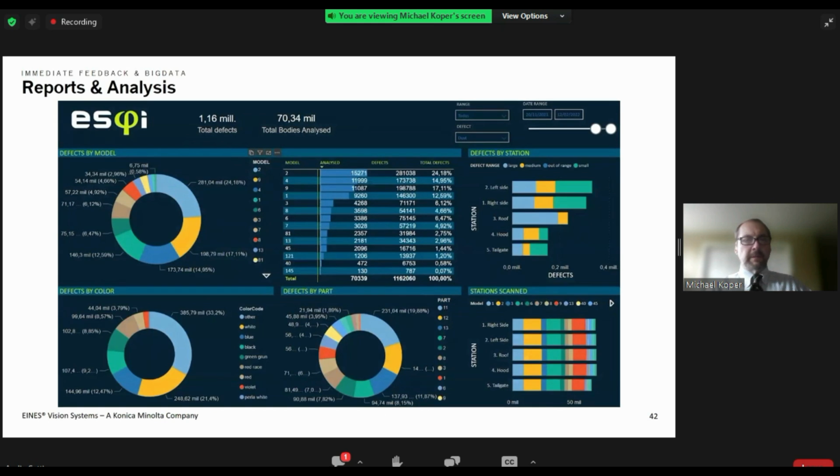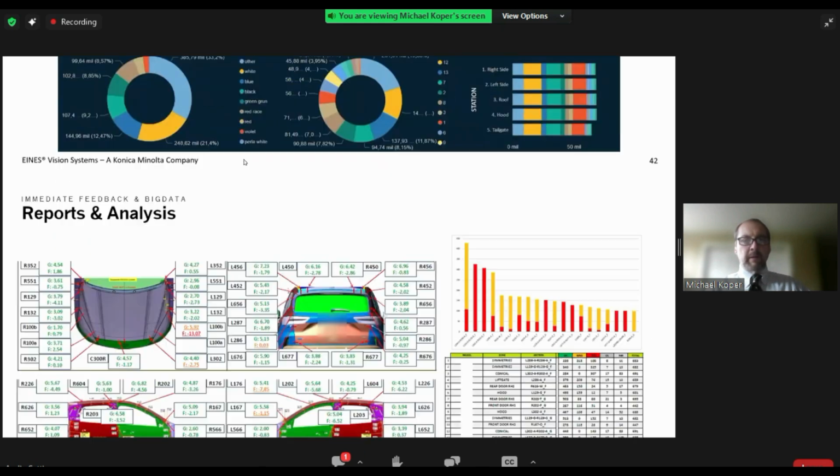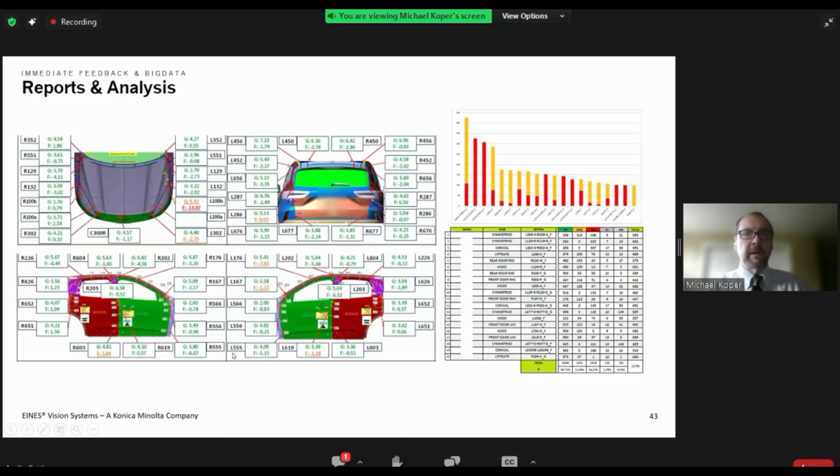And then here in our flush gap system, right, we're looking at not only the number of points. So we have several different systems that are in the working at different OEMs right now, where we're measuring up to 120 points per vehicle. Some of them are up to 210, I think, is the highest that we've gone. But just make sure that you understand that there's a time from when you can do the measurement to the display. And typically I need about 3 meters behind the tunnel in order to display. So about 18 feet, I can get most all of the displayed information, in case there's a fitter that's prepared for that.